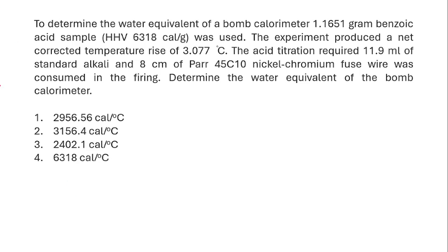And here comes a problem. To determine the water equivalent of a bomb calorimeter, 1.1651 gram of a benzoic acid sample having the heating value of 6,318 calories per gram was used. The experiment produced a net corrected temperature rise of 3.077 degrees Celsius, and the acid titration required 11.9 ml of standard alkali, and 8 centimeter of Parr 45C10 nickel chromium fuse wire was consumed in the firing. Determine the water equivalent of the bomb calorimeter.